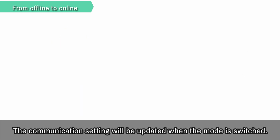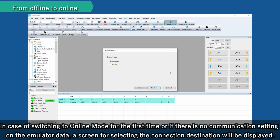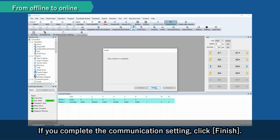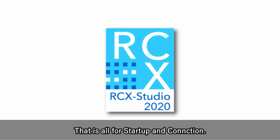The communication setting will be updated when the mode is switched. In case of switching to online mode for the first time, or if there is no communication setting on the emulator data, a screen for selecting the connection destination will be displayed. If you complete the communication setting, click Finish. That is all for startup and connection.